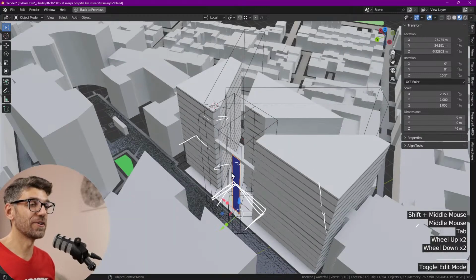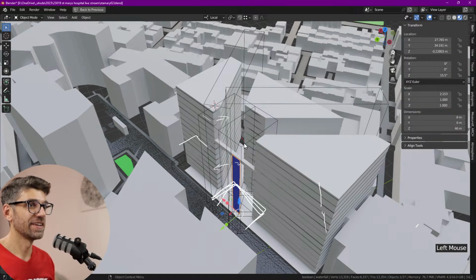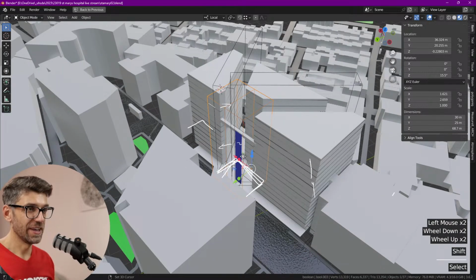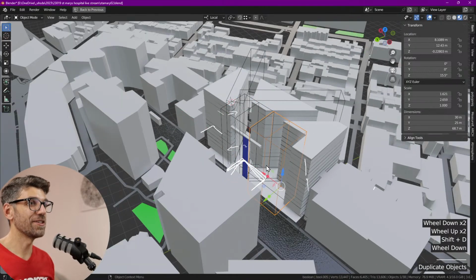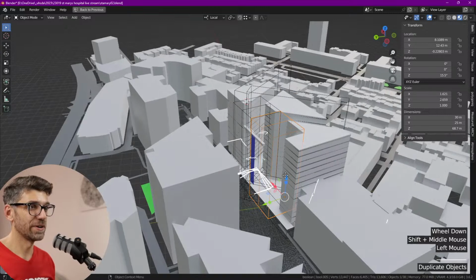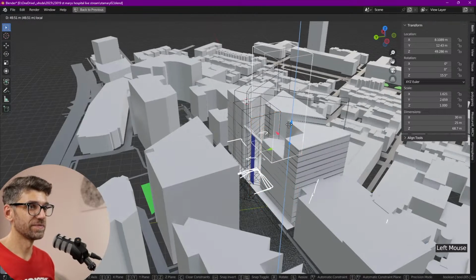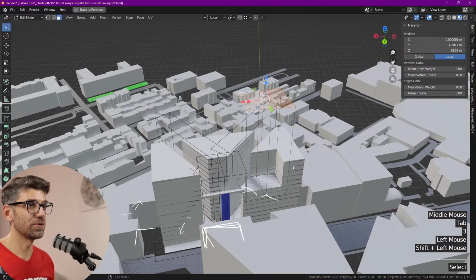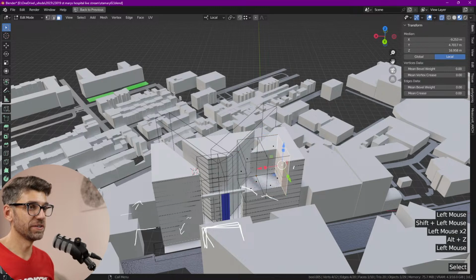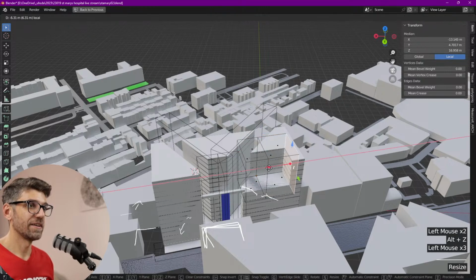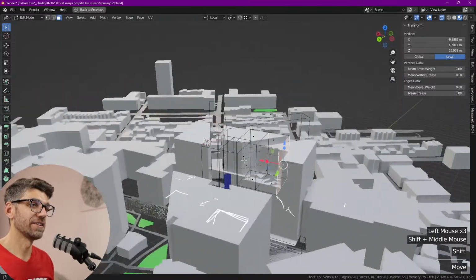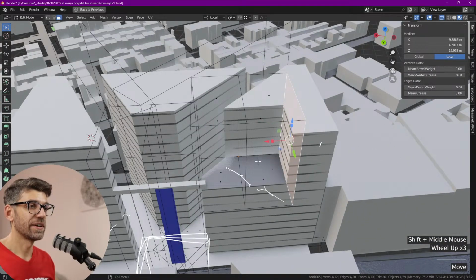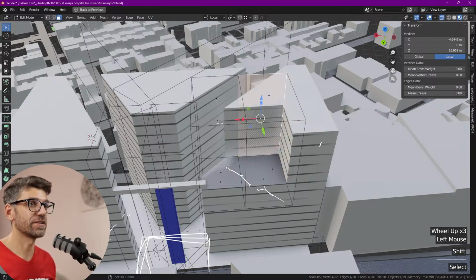Now from that space on, let's continue this wonderful Booleans work that we have. By duplicating this Boolean over here, we're going to start stepping back some of these buildings. Not that much, although that's pretty interesting too. But let's go now from the 10th floor. So we've got some kind of terrace happening from that edge over here. So let's go into editing this Boolean. And then maybe we do stay like that a little bit. And the plaza is very internally facing in here.